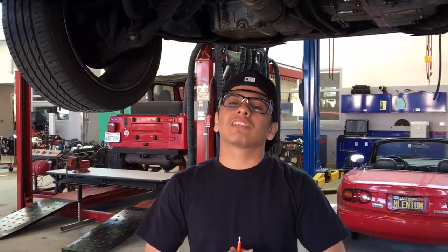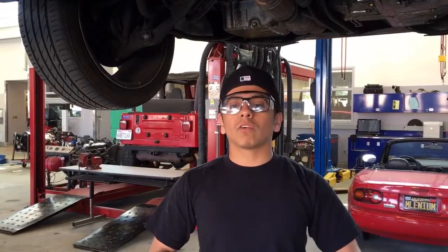The sensor does not actually measure oxygen concentration, but rather the difference between the amount of oxygen in the exhaust gas and the amount of oxygen in air. Rich mixture causes an oxygen demand. This demand causes a voltage to build up due to the transportation of oxygen ions through the sensor layer. Lean mixture causes low voltage since there is an oxygen excess.